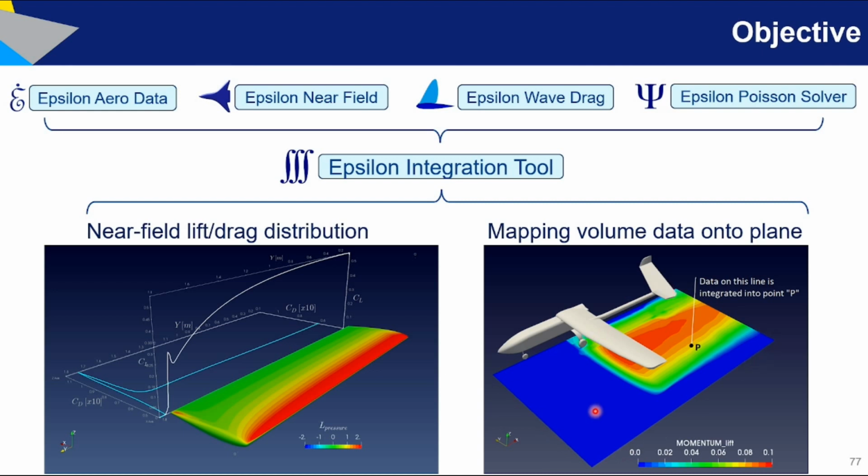And of course, you do that for all the points that build up the plane. So basically, you are condensing all the 3D distributed information into a plane. This gives you a sort of cartography of the aircraft and its effect on the airflow. So it's quite useful to analyze complex geometries or even simpler geometries and to understand the physics with just a quick sight.